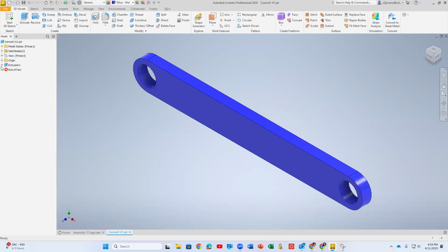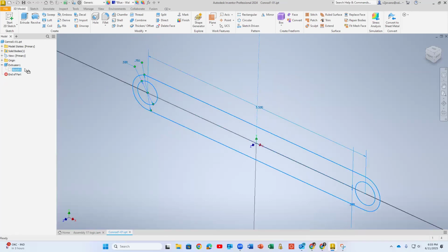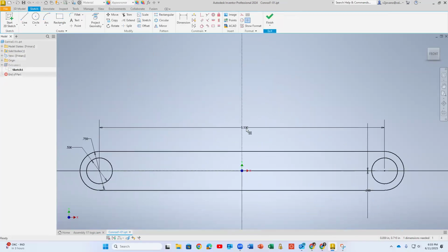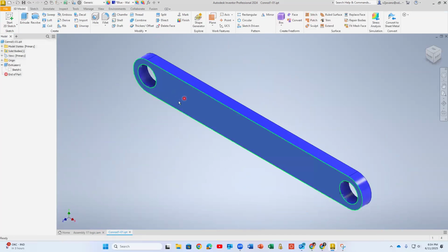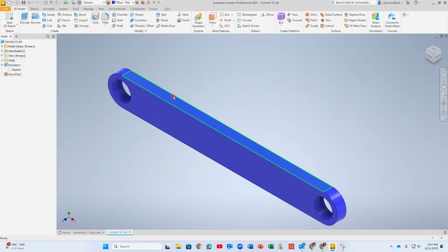However we defined all the sketches. Right now you see we have these sketches inside of it. And if you click on any of them, you will see what is D1. So I use this 75. Any dimension that you have, it will show in that dialog, and also the extrude and some other different things. So that's very interesting to know.